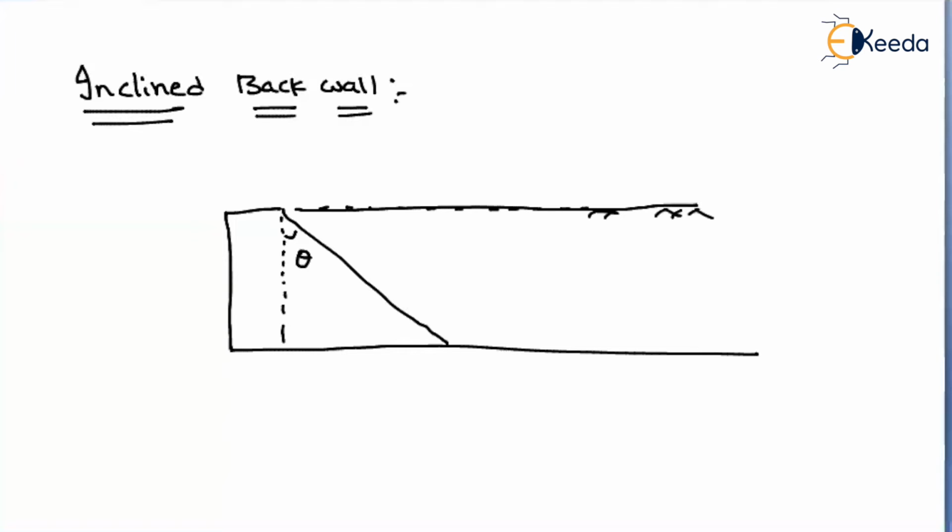That means first we will draw a vertical line that is parallel to the toe of the retaining wall. So from the toe of the retaining wall, let us draw a vertical line. If you see this part, imagine it like a vertical wall is here and the soil mass is retained. Because of this, you will find out the earth pressure like this. Let us imagine the magnitude is P. It can be either active or passive, it's up to your wish. But as of now, let us just remember it as P.